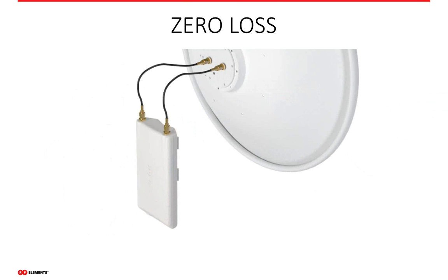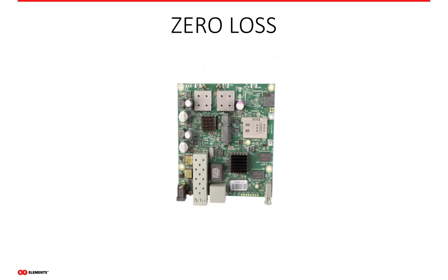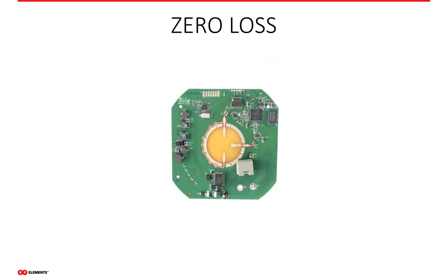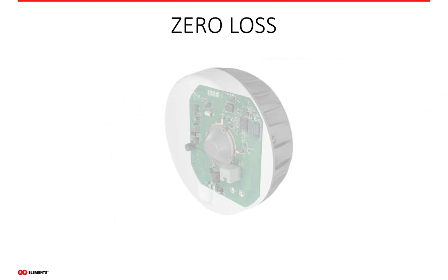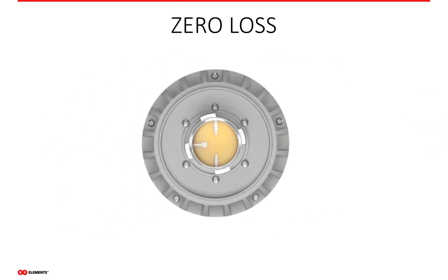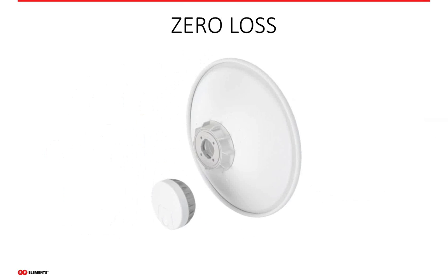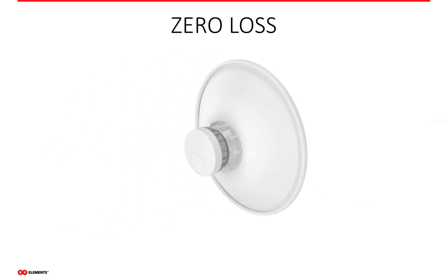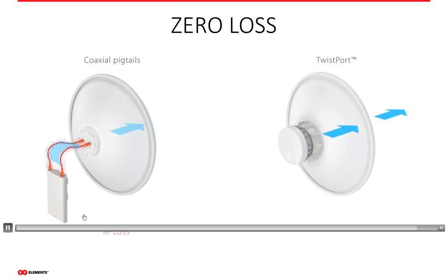So by going to 23, 24, maybe even 25 to counter the loss of the pigtail, you're unable to maintain those higher MCS rates. So it's really important to have zero loss, so that the TX power of the radio can be as low as possible and still deliver the end result, the EIRP max that you're looking for if necessary. It's a much more efficient way of building radio systems. Pigtail systems are really old school, and the industry needs to change their ways.